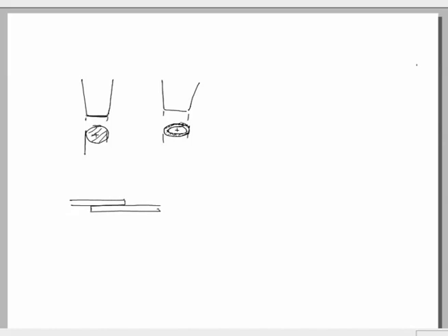Let us consider these two plates being touched by this sonotrode; then the welding will take place on an elliptical cross section, that is, the shape of the seam resembles the sonotrode shape, and this shape can even be square or some other configuration as the requirement or the workpiece shape demands.